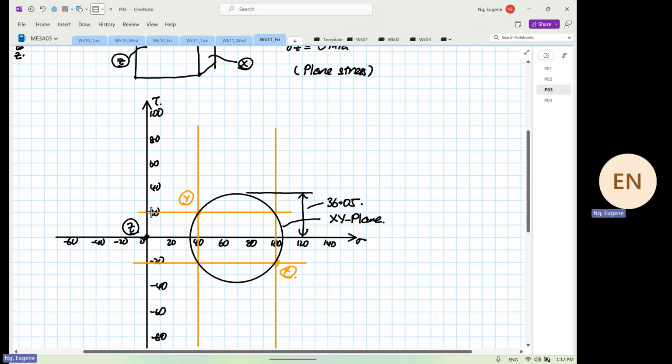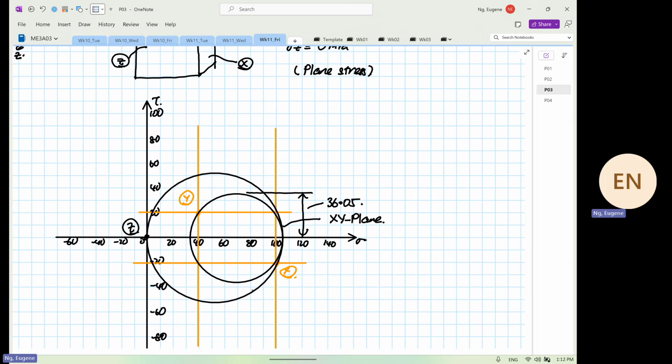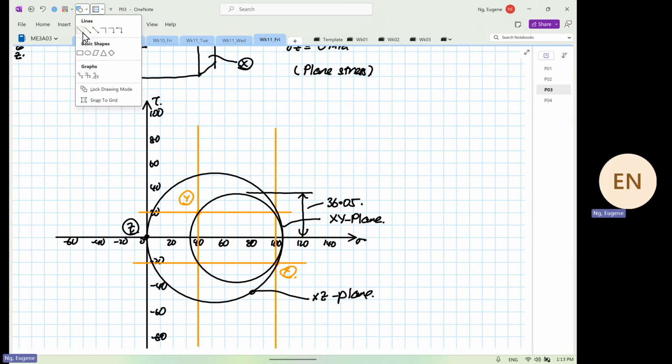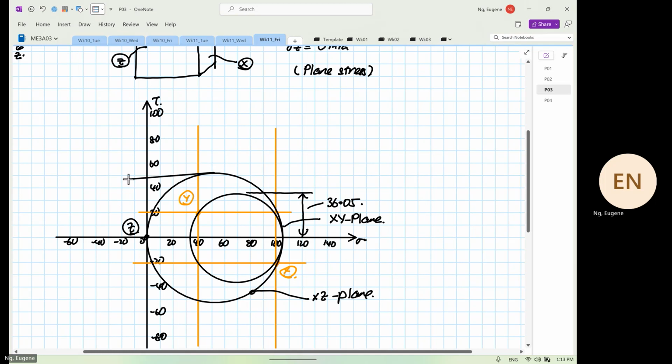And this is exactly what happened to the case which I was an expert witness to. The engineer ignored the next circle. And the next circle is only possible with a construction of 3D Mohr circle. So now this circle over here belongs to what plane? It belongs to your XZ plane. And when you now have this circle, your tau max becomes this value over here.